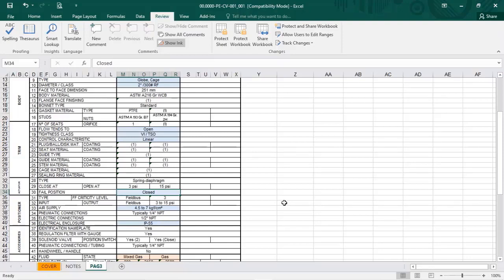We can have liquid at the separator vessel and eventually send the liquid to the customer. So instead of having a valve with fail position open, it's safer to have a fail position closed. If something goes wrong, the valve will close instead of open.